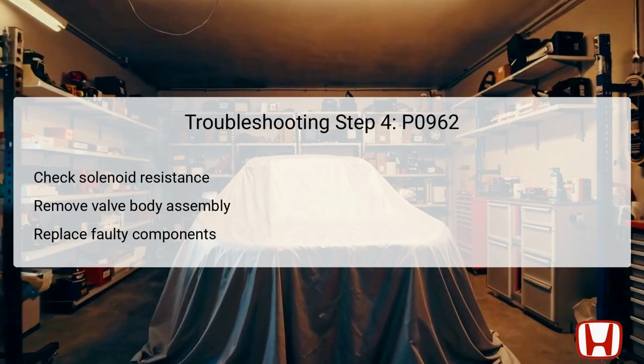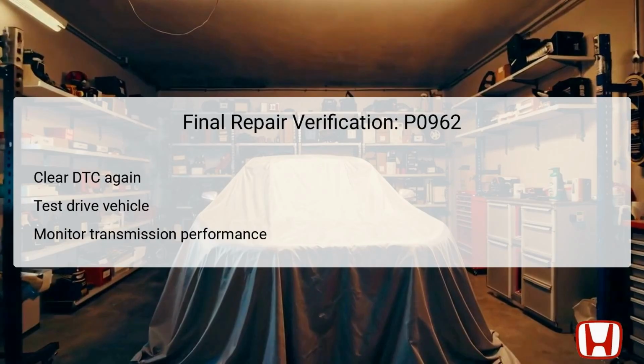Conversely, if the resistance is outside this specified value, the solenoid valve itself is faulty and necessitates replacement of the valve body assembly.